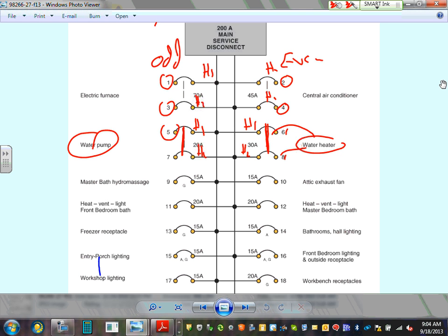Because when I told you guys, like for the water heater, say circuit 1 and 3, not 1 and 2, or 3 and 5, or 2 and 4, 2 adjacent odds or 2 adjacent evens to get you the 240. Can I have thumbs up, chat? Because you can't believe how many times we reach a commercial project and I see students circuiting a 3-phase load and they're using 1, 2, 3 as the 3-phase. 1, 2, 3 will never give you 3-phase. It has to be 1, 3, 5 to get you 3-phase. Does that make sense? Very important.